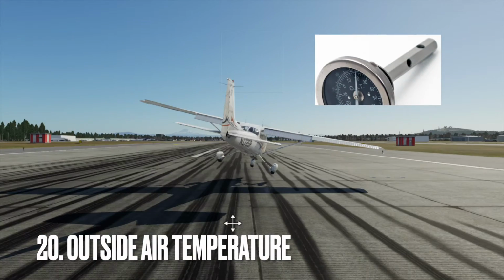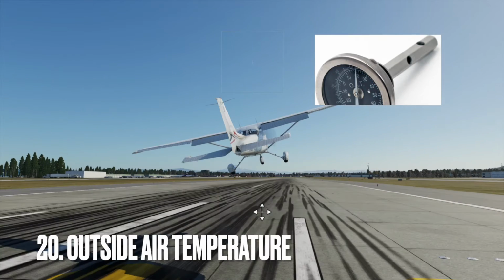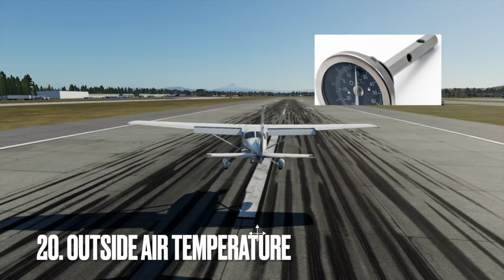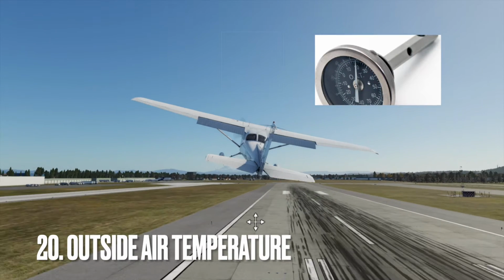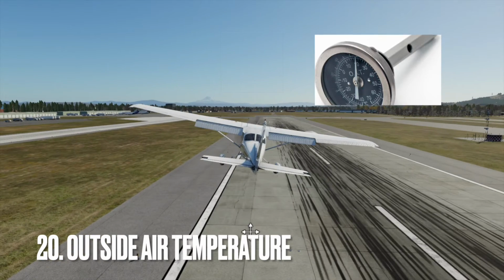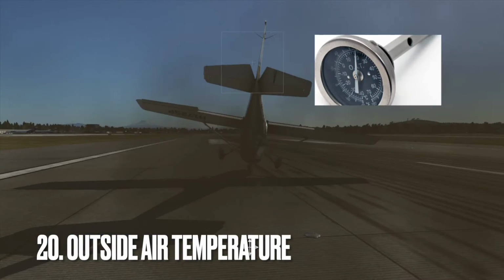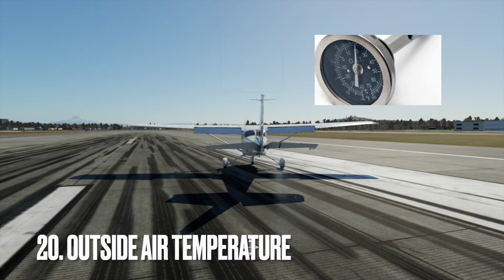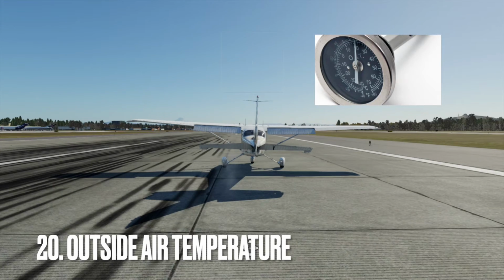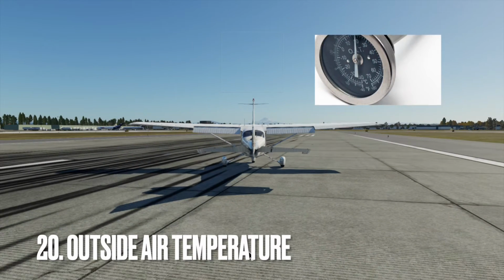The outside air temperature, OAT gauge, displays the temperature outside the aircraft. Pilots use the OAT gauge to monitor ambient temperature and assess atmospheric conditions during flight. For example, during climb, the pilot monitors the OAT gauge to determine temperature changes and anticipate icing or turbulence conditions. Monitoring outside air temperature helps pilots make informed decisions regarding aircraft performance, fuel consumption, and weather avoidance.